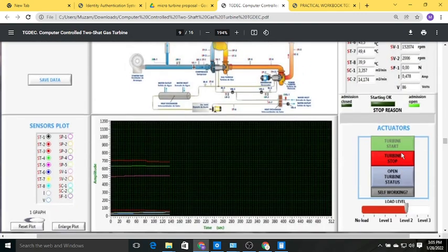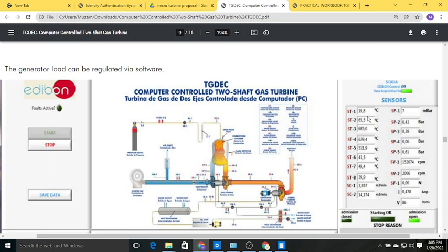You can see that in the manual. Let's suppose we have 19 ambient temperature, 65 at the compressor, and 650 after combustion. After the first turbine, there is temperature loss and also pressure loss. We have 4.43 bar pressure after compression, and after the turbine the pressure reduced to 0.39 bar. Okay, I think pressure is not calibrated up to the mark. It is not